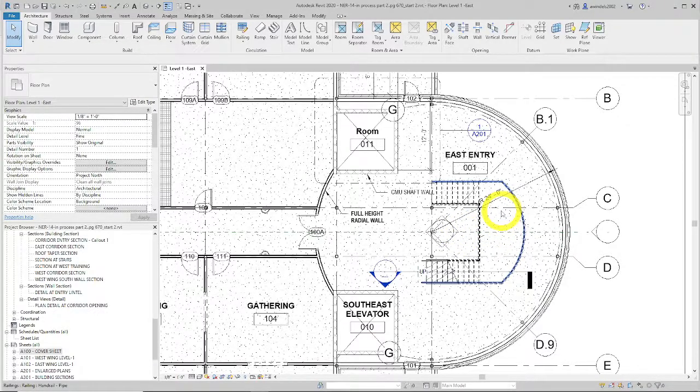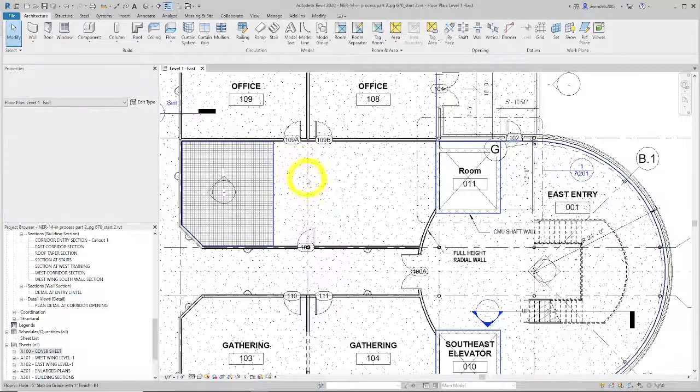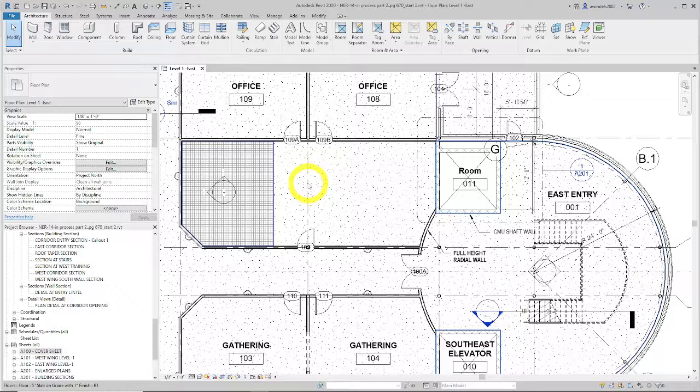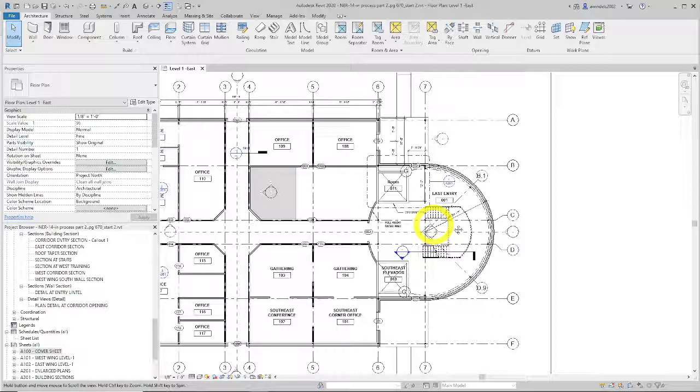Going on to page 673, we're going to do some room bounding properties. So in some situations, you don't want a wall to separate a room, for example. Like, we're going to do this later. We're going to separate this room about this invisible middle reference plane, for example, in the chapter. So let's see what they have for us here in the east wing. Zoom into the laboratory area.